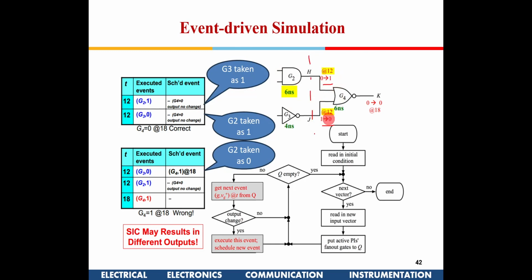If both the inputs are changing at the same time, one from 0 to 1 and the other from 1 to 0, then in a practical circuit, when I fabricate it, it is possible that the output remains 0 only, isn't it?